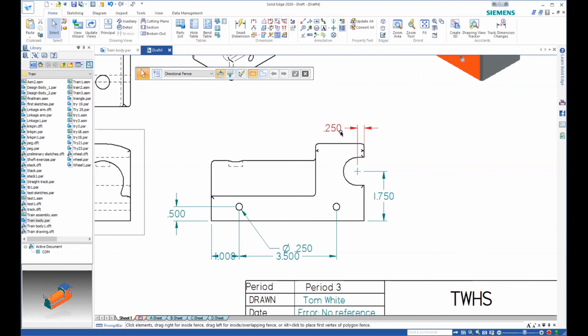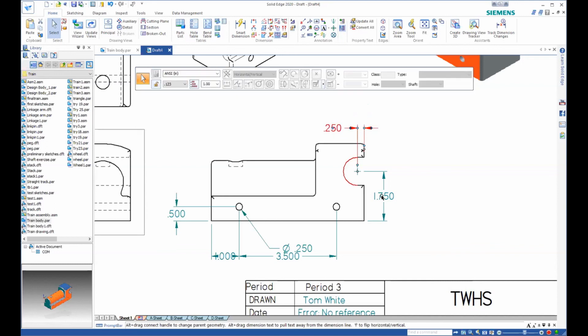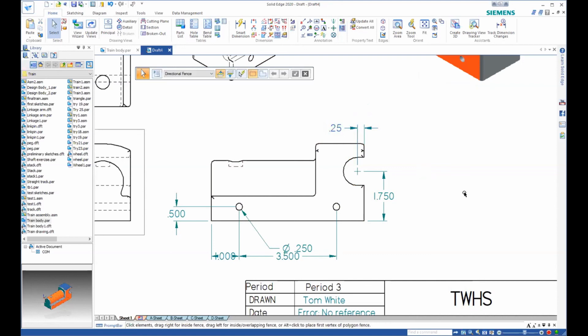And one of the things about this is, having the 0 at the end implies a few things, but it might be better to say, okay, we don't need those. We're only going down to the 100th of an inch. And then you would say, I only need 2 decimal places. So it would then change, and it declutters your drawing a little bit.